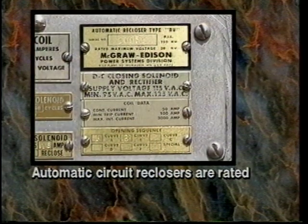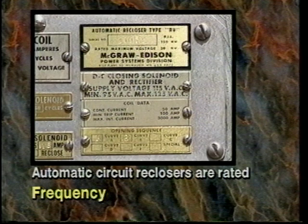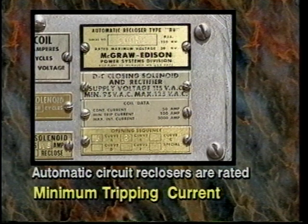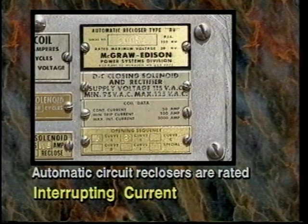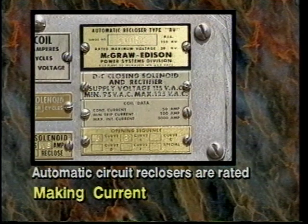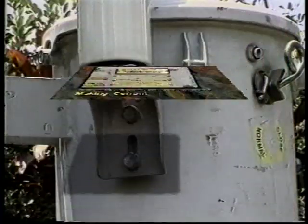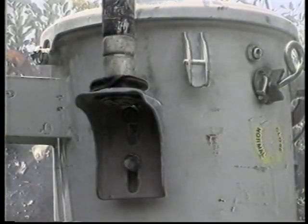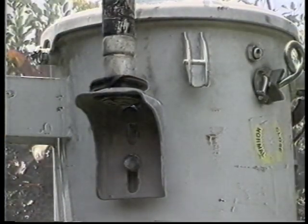Automatic circuit reclosers are rated in terms of various voltages: frequency, continuous current, minimum tripping current, interrupting current, and making current. Warning: in operating a recloser, the limitations imposed by a given recloser rating must not be exceeded in any respect. Otherwise, excessive maintenance or unsatisfactory operation may be experienced.